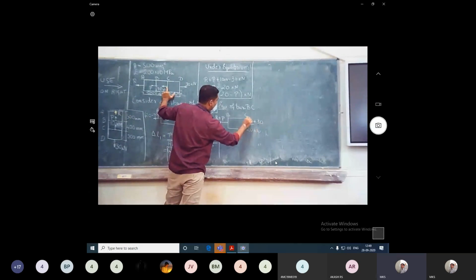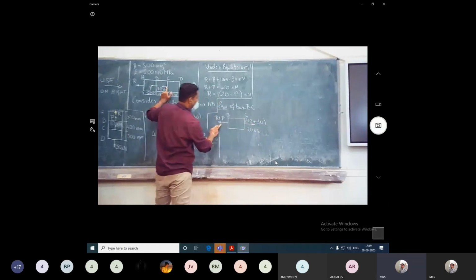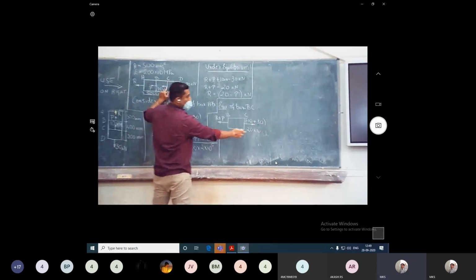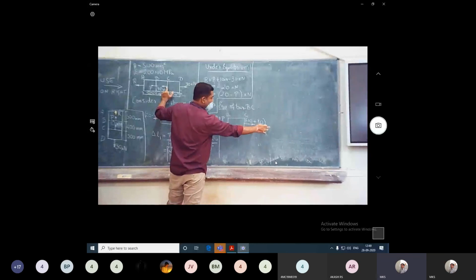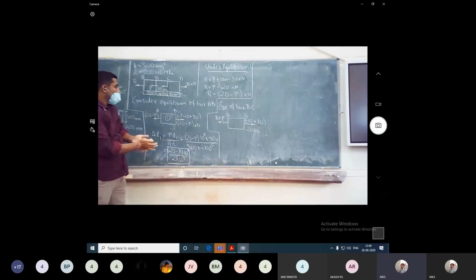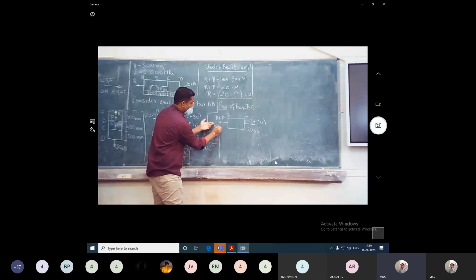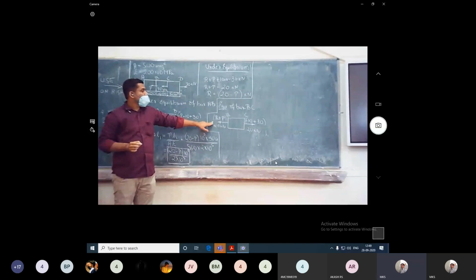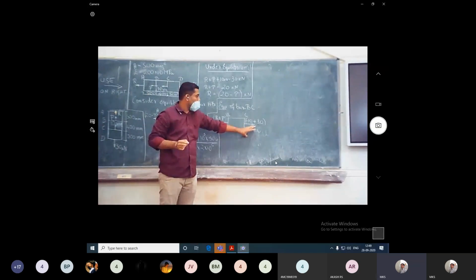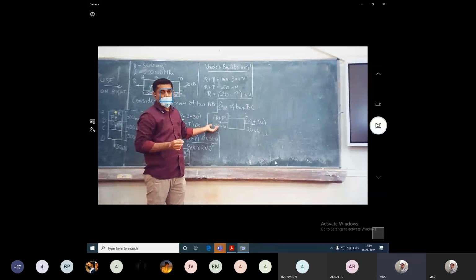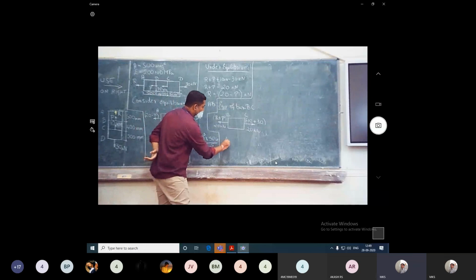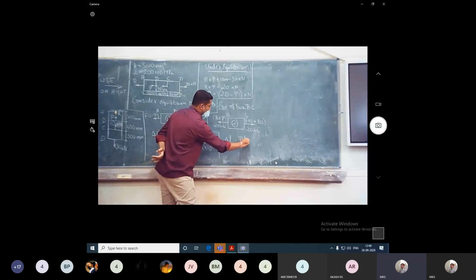So it is 20 kilonewton. So what is the direction? Direction it has to be the same as this. Since 30 is greater, it is tensile. It is 20 tensile. So what is the force in the other direction? It has to be the same, 20 kilonewton. So R plus P should be equal to 20 kilonewton. Right, now coming from one side is enough. So it should be the same as that in the other direction also. So I'll directly write it as 20. So now you calculate deformation, so we'll consider it as delta L2, that is P L2 by AE. How much? Fine.